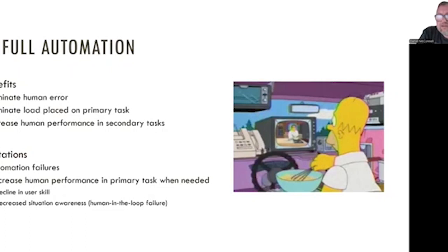What you need to have is a human operator who can intervene at that point. So we don't want to take the pilot out of the cockpit. We want to keep them there so that they can jump in and intervene at the exact moment this failure occurs, which of course means that we need to make sure that operator, in this case a pilot, is continuously informed about the state of the automation and what it's doing and when it fails. So that way, in the case of a failure, the pilot knows immediately the failure has occurred, but the pilot also knows what kind of failure it is, and therefore what kind of intervention is required.